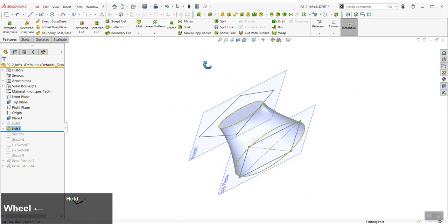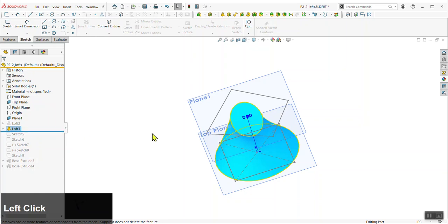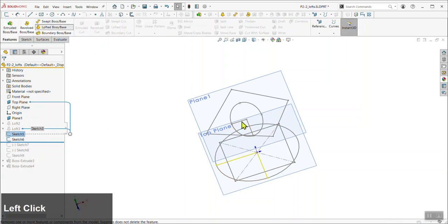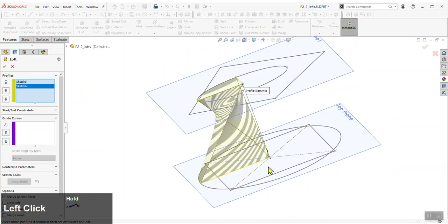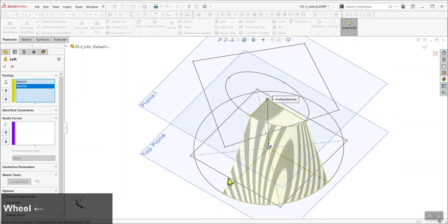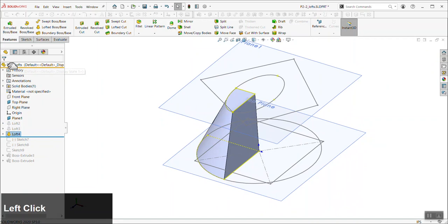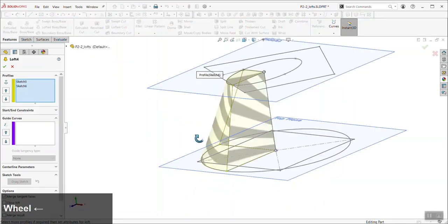And so an easy way to fix that, and the best way to address that, is actually to loft in halves and quarters. And what that does for us, so if we loft from this quarter circle to this quarter oval, it now gives us corners with which to drive our loft and guide it, and gives us a little bit more success that way. Even better with this loft would be to add in some guide curves here.